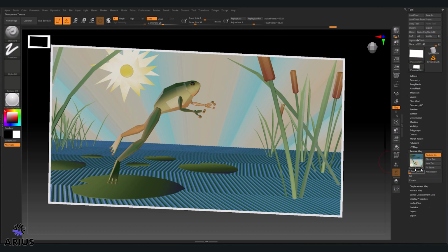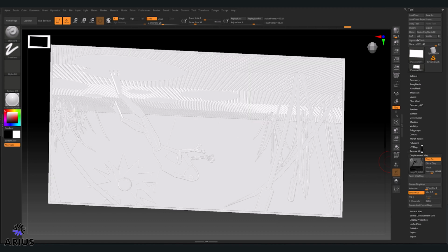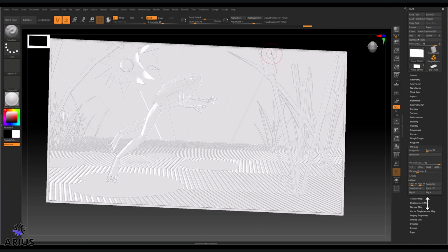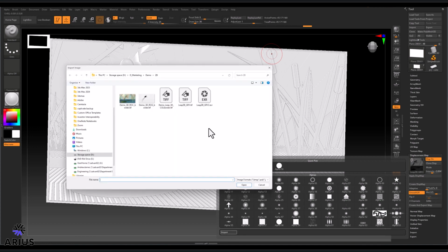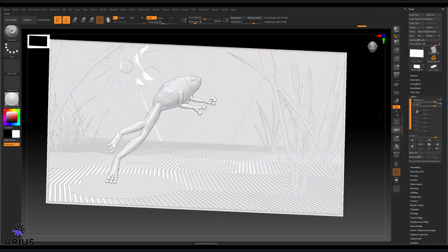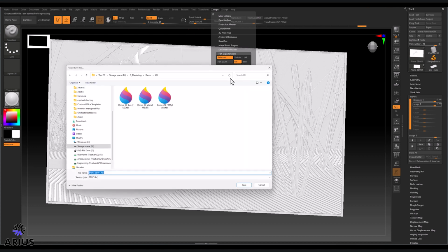If you use an external grayscale image to displace the surface, you may need to flip the UVs for it to show correctly, and then back again for the color to render properly when exported. A 16-bit TIFF or PSD will create a banded effect, so make sure to use a 32-bit EXR image to generate a smooth displacement surface. Once you have the sculpted surface complete, export the object as an FBX mesh back to your 3D app.